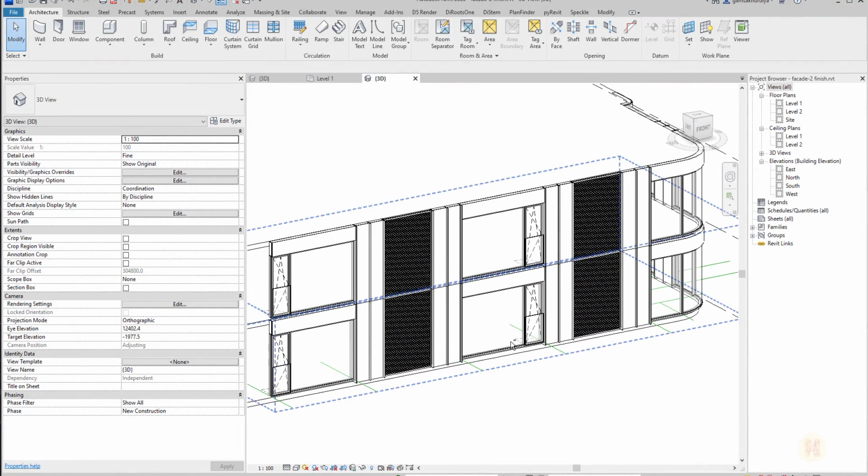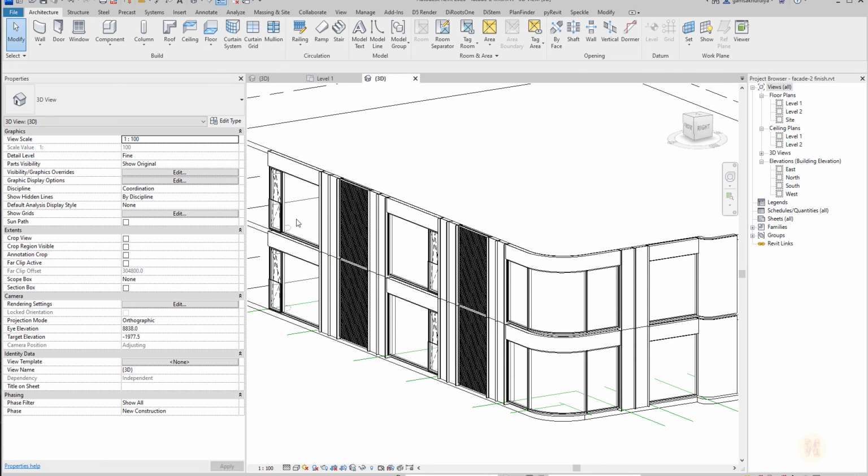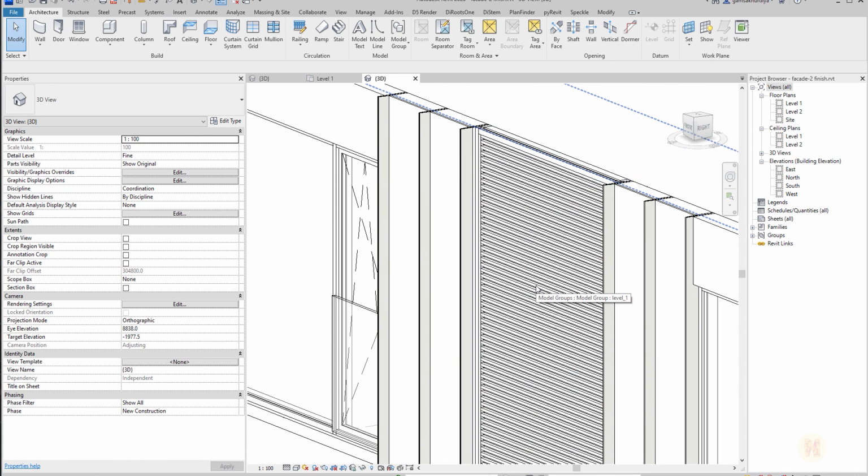I think right now you understand how you can create these facades. This is a modular facade, because we have the one module, the second one, third one, and a lot of modules. It depends on your design. For example, if you don't like these panels, you can create your own panels and place them. You don't like this radius panel, also create your own and change this module. You don't like, for example, these mullion panels here, you can create a flat one, why not? And this is what the modular facade is about.